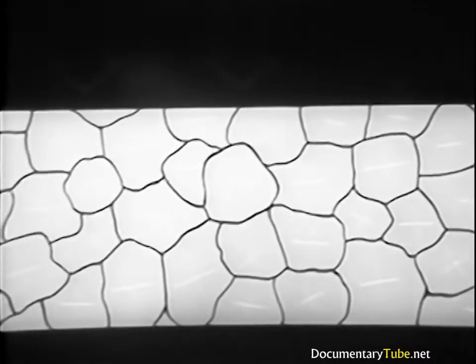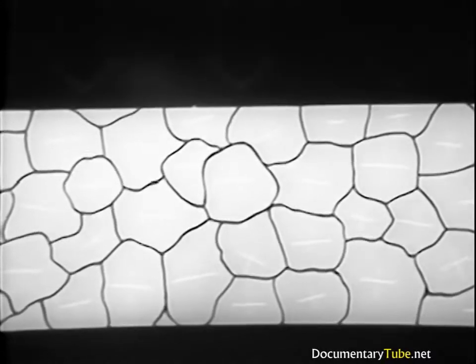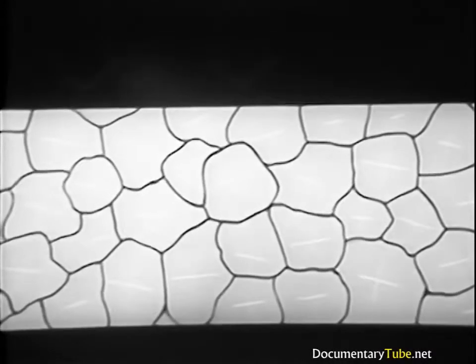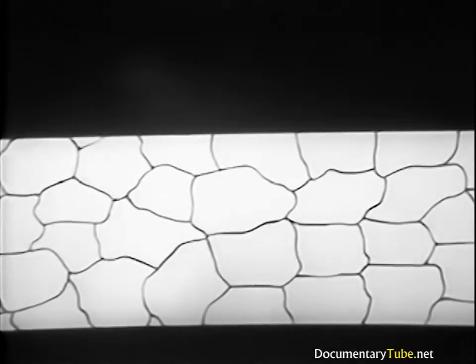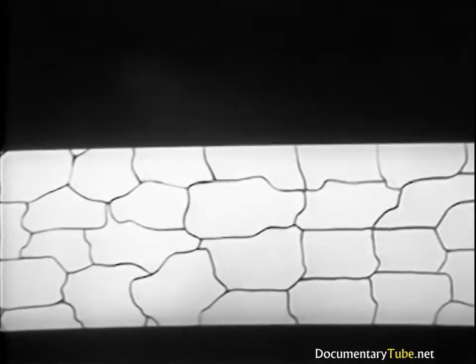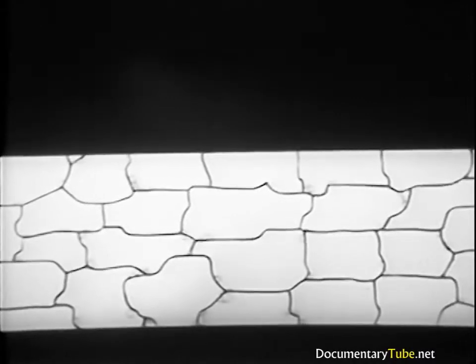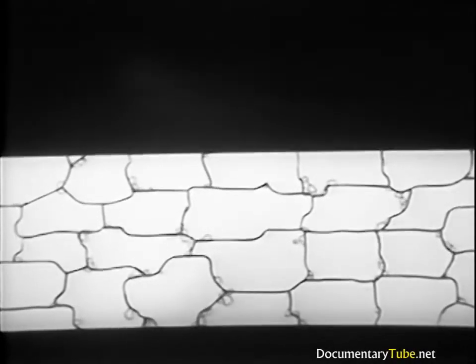When it is brought down upon the loaded table, the rubber pad transmits pressure in a fluid-like manner, forcing the metal to the shape of the dies. Under the type of load applied in the bending and stretch forming processes, the grain structure of the aluminum alloy changes in a manner similar to that shown for the cold rolling and stretching processes. The grains rotate along the active slip planes and become elongated, and the metal is strain hardened.